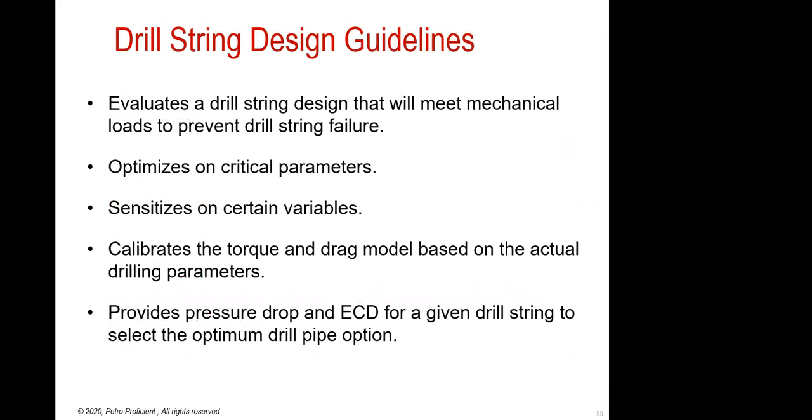These are some other guidelines for drill string. It should meet the mechanical load to prevent any failure. All the critical parameters have to be optimized when you're drilling. Then you have your torque and drag based model, so you need to make sure that your model is calibrated and up to date with the drilling parameters. Pressure drops and bottom hole ECDs are important calculations that need to be done ahead of time before you select your drill string, so that you get the right drill string.